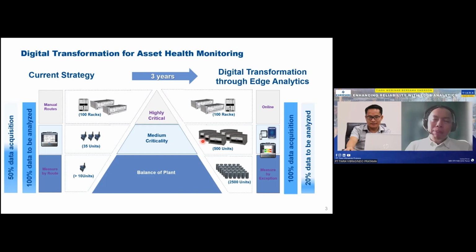It will depend on the mounting position and so on, because in a cooling tower, one of the difficulties will be the gearbox. You want to monitor the gearbox inside. Sometimes wireless might not be so suitable, because if you put the wireless inside that cooling tower near the gearbox, you're going to have problems getting the data out, getting the connectivity. That is one common challenge of mounting wireless inside the cooling tower.